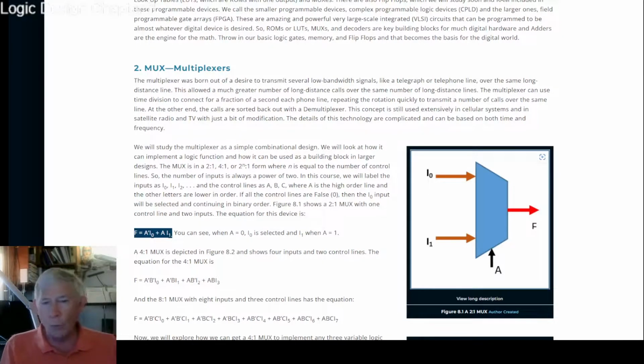And we can select which one we want to go to our actual conversion module, because in most of those cases we'll only have 1 comparator module or 1 A to D module or 1 touch sense calculation module, and we have to be able to switch between maybe 12 or 16 different inputs on our microprocessor that are connected to different pins and even some internal connections. And in order to do that, we need an analog multiplexer, which actually is like a switch that dials between, say, 12 different inputs and connects one of those to the output. In that case, we're transmitting not just a 0 or a 1, we're transmitting the actual voltage level on the wire that we're connecting. And so it varies over a continuous range.